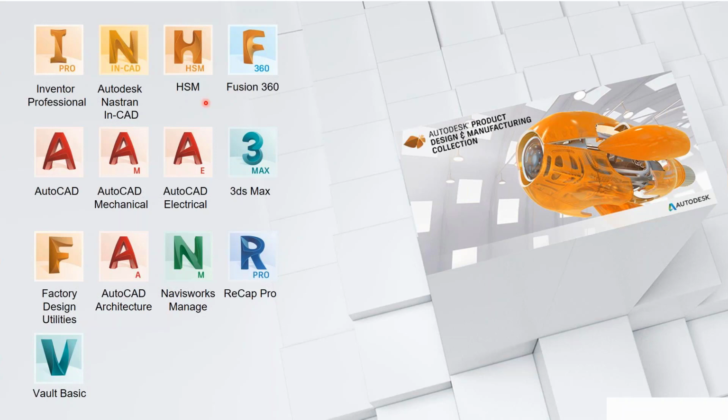Previously, you had a choice to buy or subscribe to the HSM product as a separate product, and then you could choose between HSM Ultimate and HSM Premium. That was 2 different levels of the software, with 3-axis machining or up to simultaneous 5-axis machining. But today inside the collection we have put the Ultimate version. So there is no additional module for HSM. Everything is there already from the beginning.